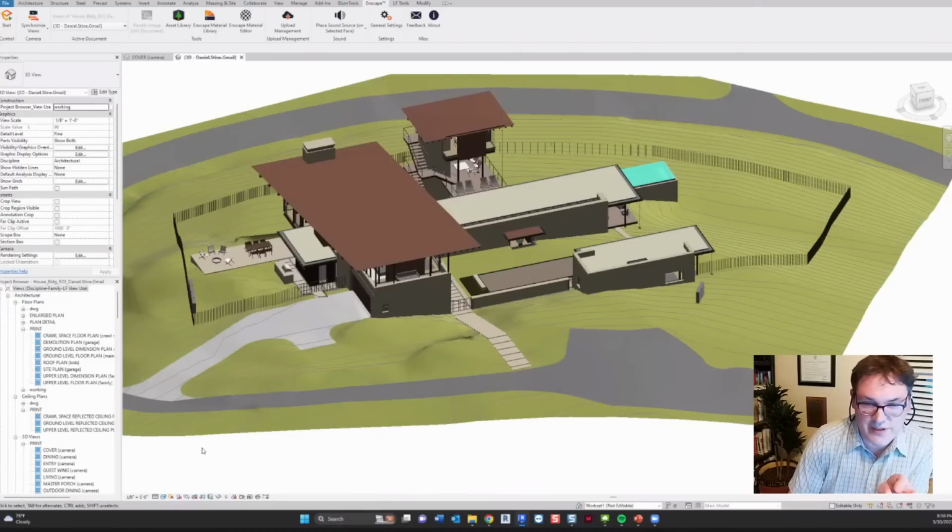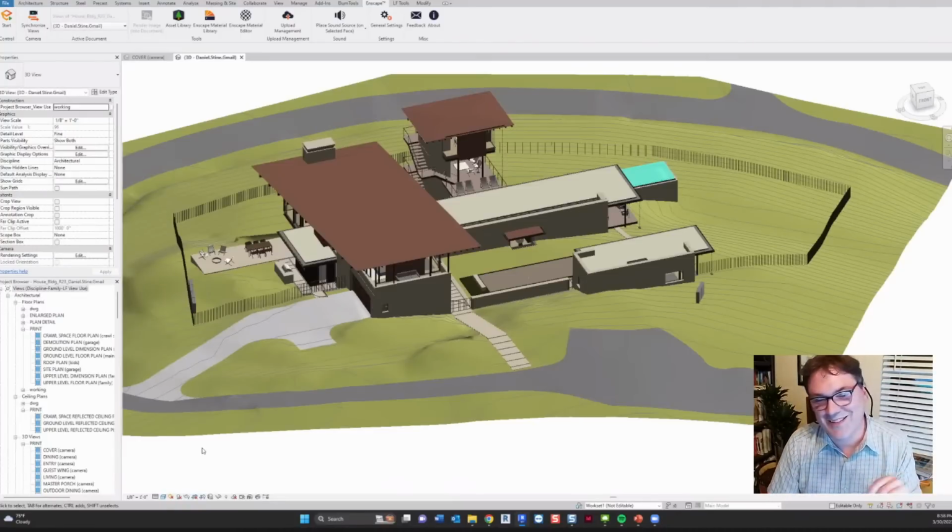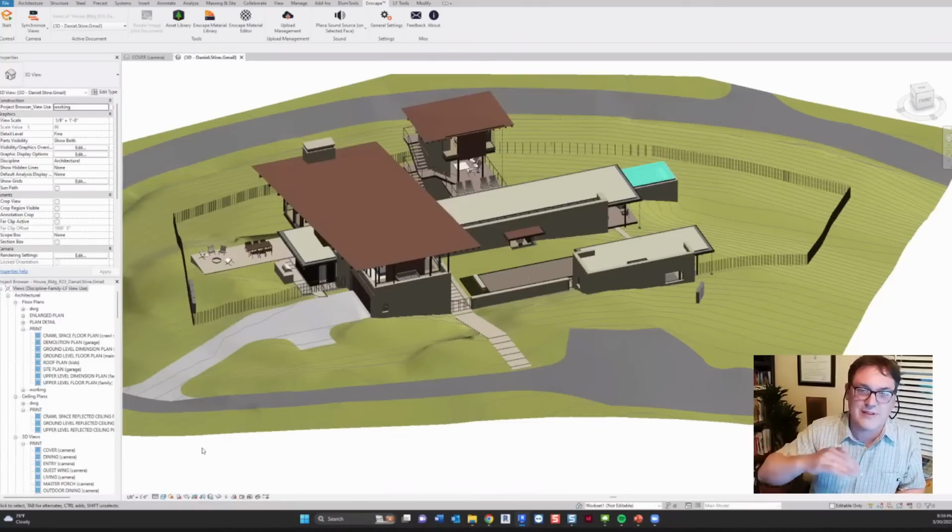Of all our linked projects, every single project, unless it's a bigger multi-building project, has two Revit models all the time, every time. There's a building model and a site model. On my YouTube channel, which has a couple hundred followers, I did a shared coordinates series and showed this workflow. In the site model, there's a level that's called sea level. When we link in the CAD file, the 00 for the CAD file is at sea level, and the geometry is at whatever level it is relative to sea level. And then that's linked into the building model.